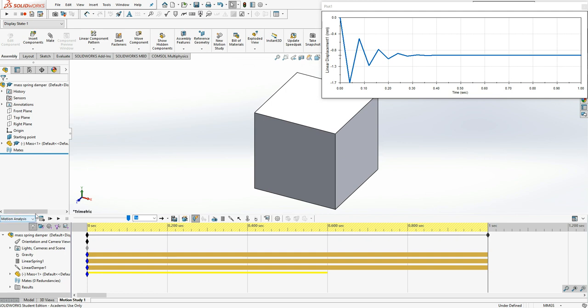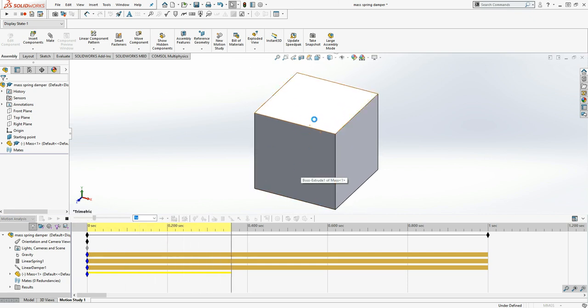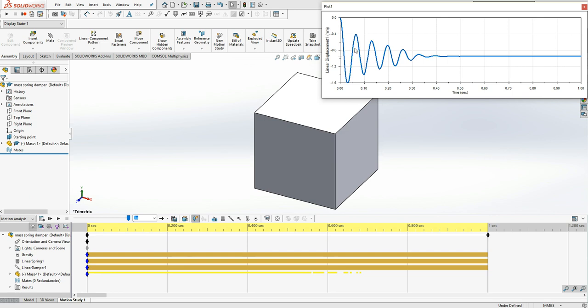So I've clicked OK and let's recalculate. See how this nice smooth motion is occurring? Now you look at that. Questionable. You see some of these oscillations here. I can't really zoom into that area, but you see this point here where it almost turns into a line. Some could argue that that is actually an error, where the iterations weren't sure where it was going to be, similar to when we had a huge time step on the first order system.